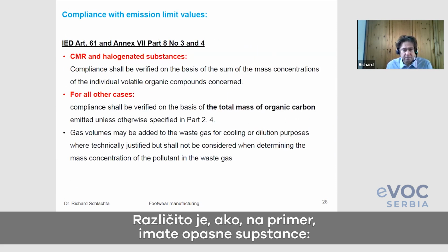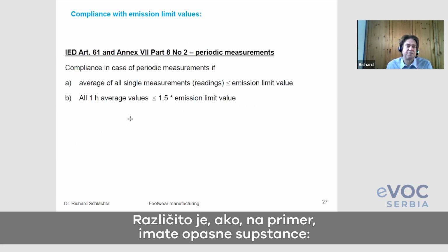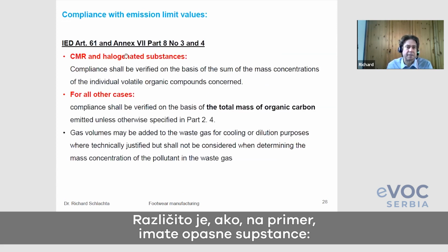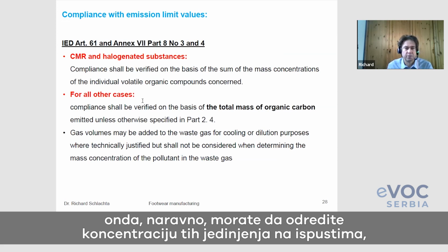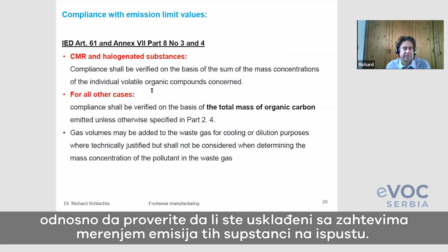That is different if you have such dangerous substances. Then, of course, you must determine the compounds in the stacks, and it is necessary to carry out the compliance check by emission measurements at the stack.